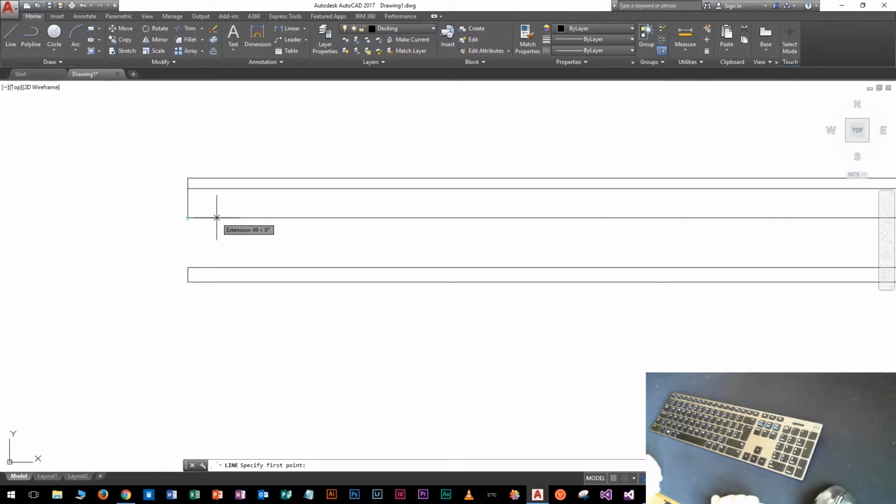I haven't clicked anything yet, and type in 44, and we are now drawing 44 away. It's measured away 44 millimeters. Follow that 45 degrees down, and where they intersect, click done. Pick up the offset tool, and I can see that I should be offsetting by 12.